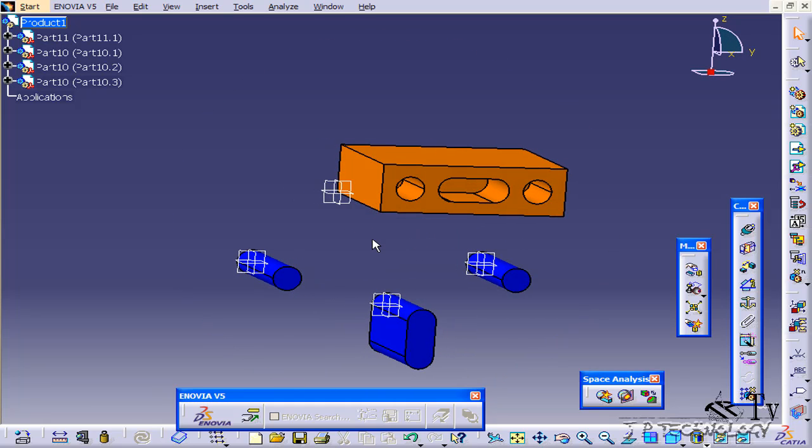Now with this tool, personally it's my favorite one for creating positional assemblies. It's really quick, really easy. It works like the other ones, where the first one that you click is the one that's going to move. So you click this one to move it into this one. And it allows you to quickly and easily snap components in, bring everything together, and create a positional assembly. Now saying that, you also have to go around using the snap feature in certain situations a different way to get the results that you want.